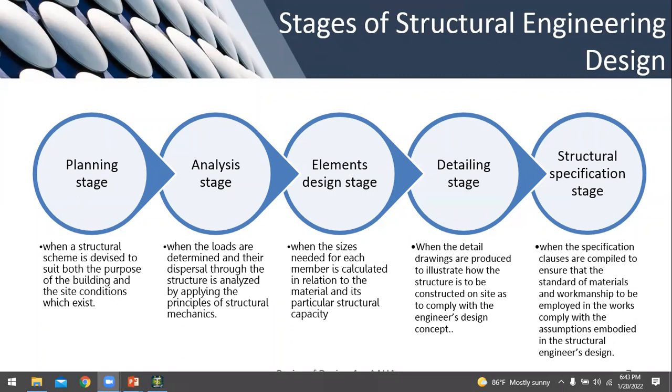Let's say someone is calling and asking, okay, we have a G+2 building with a column there, is it okay to provide 4T16 bars, or shall we increase to 4T20 bars? That is totally different. The question is wrong, because it is subjective. Depending on your structural modeling, structural concept, and the load path, everything will change. For example, you may have a column in a 3-story building that sometimes needs only 4T12 bars. You may have a column there that needs 4T32 bars. It depends.